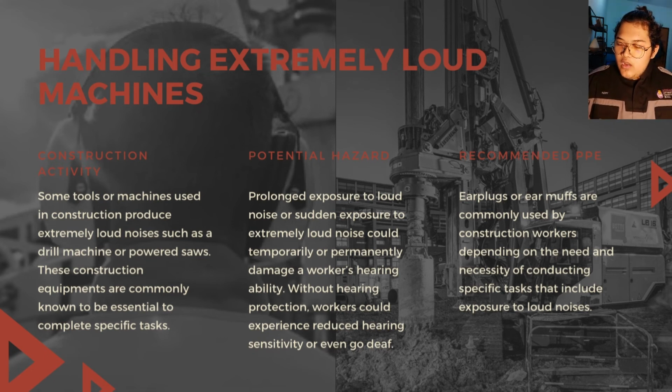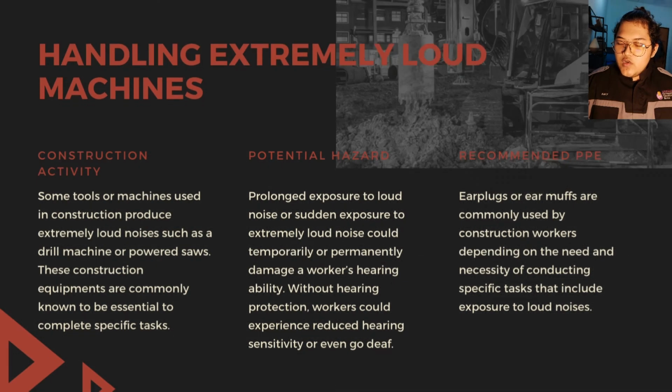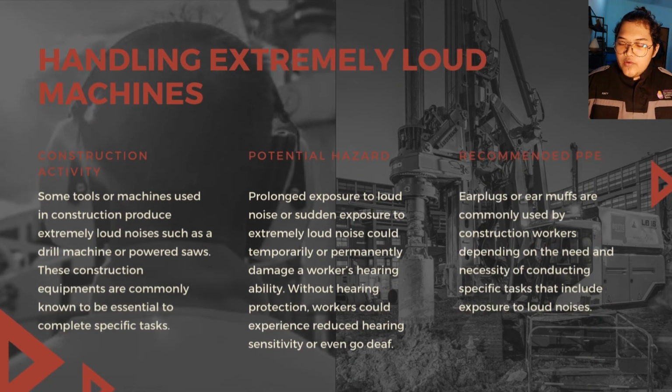Prolonged exposure to loud noise or sudden exposure to extremely loud noise could temporarily or permanently damage a worker's hearing ability. Without hearing protection, workers could experience reduced hearing sensitivity or even go deaf. The recommended PPE to be used are earplugs or earmuffs, which are commonly used by construction workers depending on the need and necessity of conducting specific tasks that include exposure to loud noises.